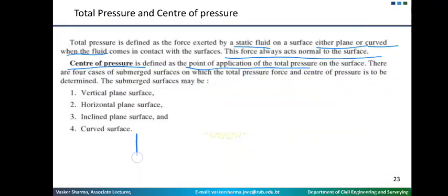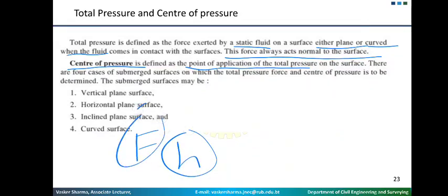Total pressure is usually given by force, and center of pressure is usually given by the height. What is the force? That is the total force, the total pressure. And at what point is that force acting? That is your center of pressure.